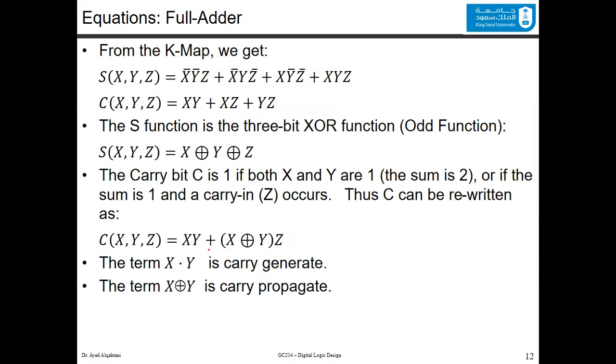Now, it's good to mention that X ANDed with Y, which is this term, is called a carry generate function. This part here, which is X XOR Y, is called a carry propagate function. And we will see this more in the coming slides, especially when we talk about the carry look-ahead adder.